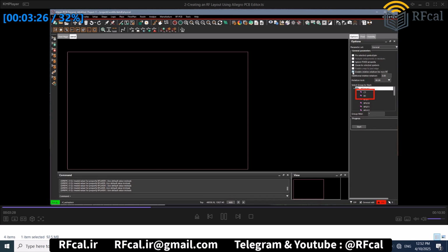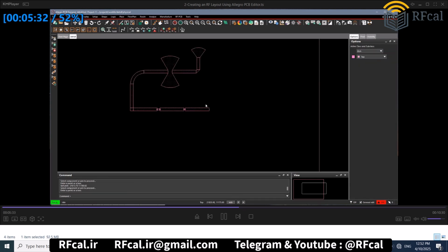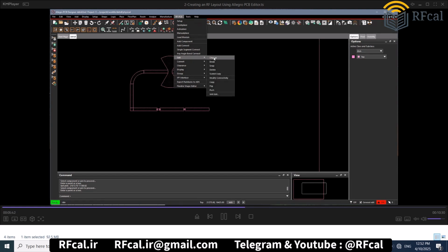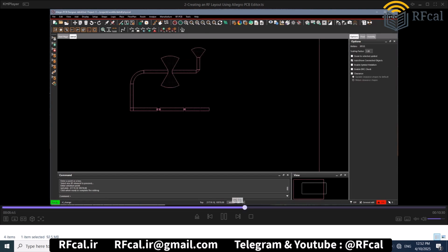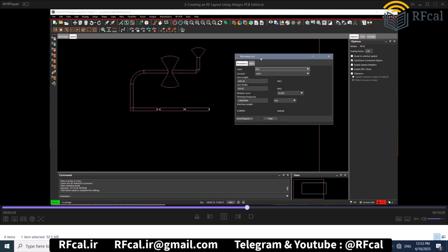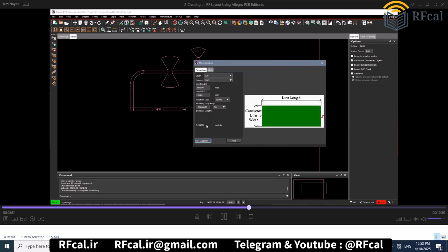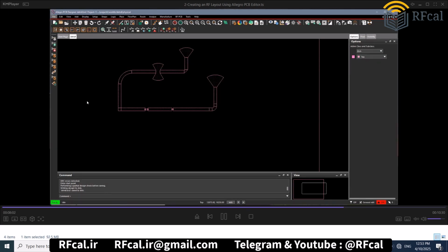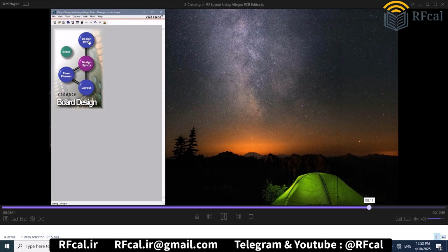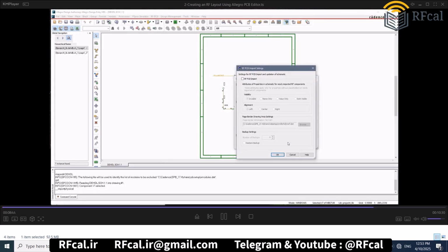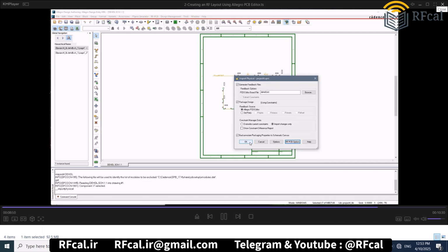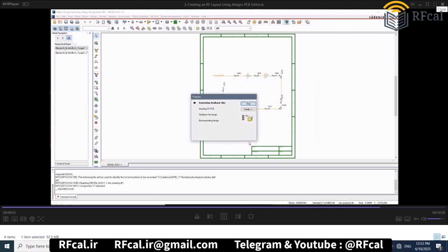That is the capacitor and resistor, and that component again did come from the schematic but can also be edited here in the layout. So let's take a look at the RF PCB edit change command, and I'm going to select this M-line component, and we'll display our GUI form and select the show diagram. Inserted RF components into the Design Entry HDL schematic. Into the RF PCB options tab here, and we make sure that we have the RF PCB import option turned on. Next thing we'll do is click OK to bring the changes in from the RF layout through the packager, and we'll update our schematic.